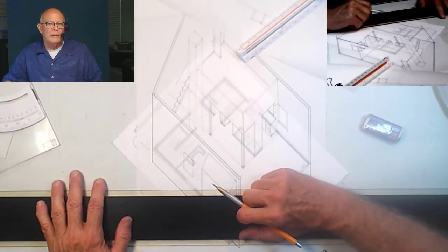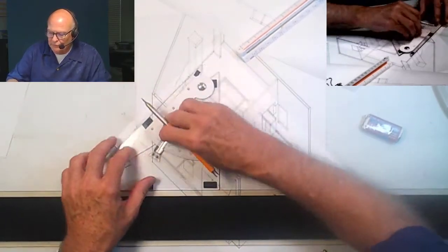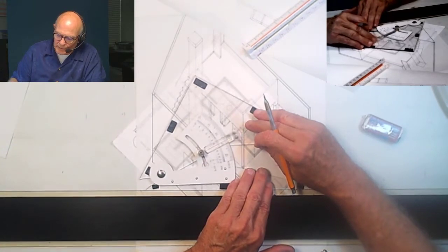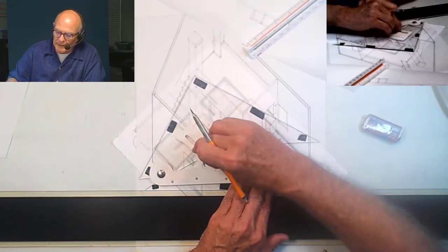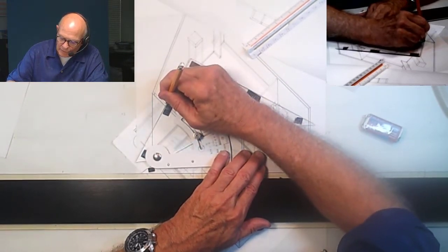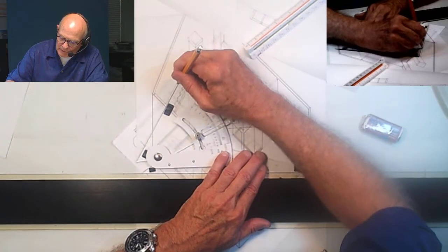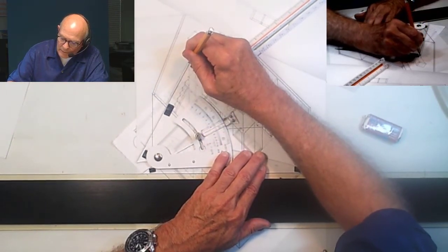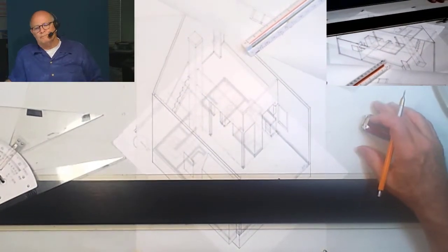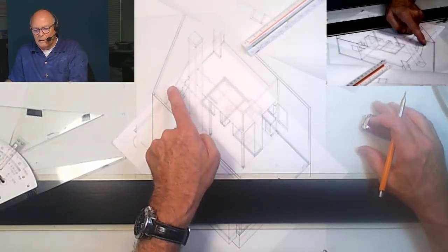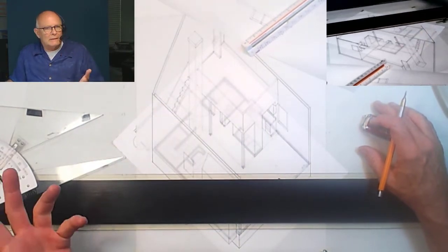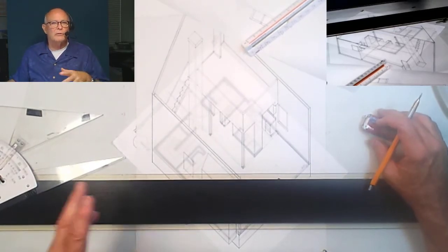Now, if I needed to put in a handrail, it would be pretty simple. I have the slope. I'm just going to copy the slope again because we know that that handrail needs to be at 42 inches above the nosings of each stair. So if I do this, just bring a little bit below that. There we go. I've got a wall on this side, handrail on that side, and stairs connecting the two together. It's a little bit of detail, but it's important to understand the mechanisms.